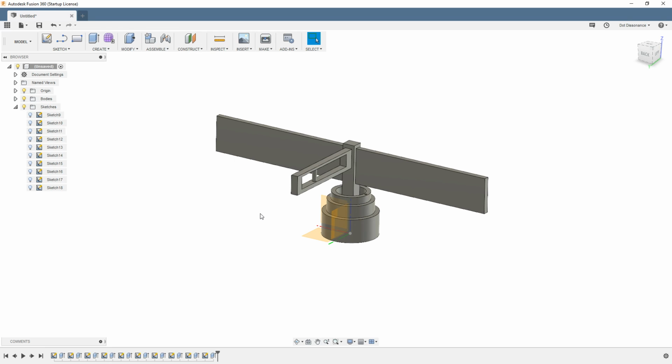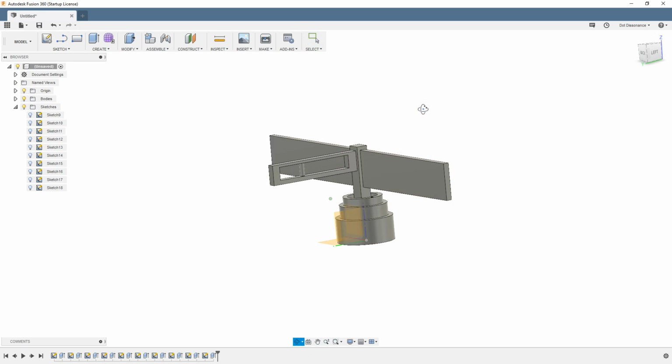I want everybody to understand: click on background, click on sketch, click on plane, make a two-dimensional shape, leave sketch, extrude, using whatever parameters you need to, hit OK, do it again, right? Sketch, plane, extrude. Sketch, plane, extrude. Or pick your plane first, sketch, extrude, right?